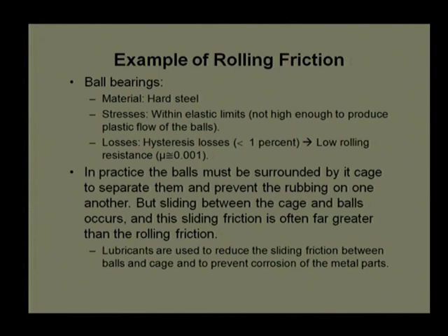However, we know rolling element bearings come with cages, or separators. We provide a cage to separate the rolling elements. The reason is that if one rolling element disturbs the other, as in fully complement bearings, load carrying capacity will increase, but there will be chances of more friction due to rolling between two surfaces itself. They will start retarding each other's motion and create a high coefficient of friction at the interface.